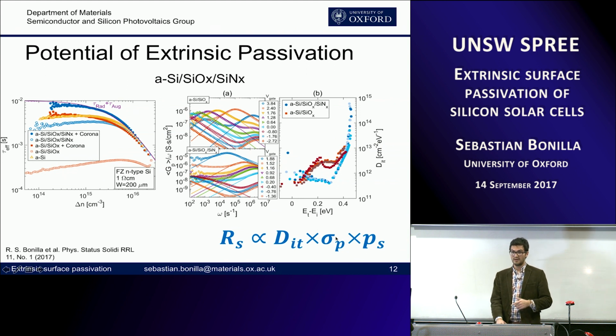And this is what I want to make an example of today: this DIT, at least in every measurement that we took, so here is an example of 3 different measurements, and we measured a few more, and in all cases we saw that it was a correct measurement. The DIT was indeed above 10 to the 11, which is quite high.